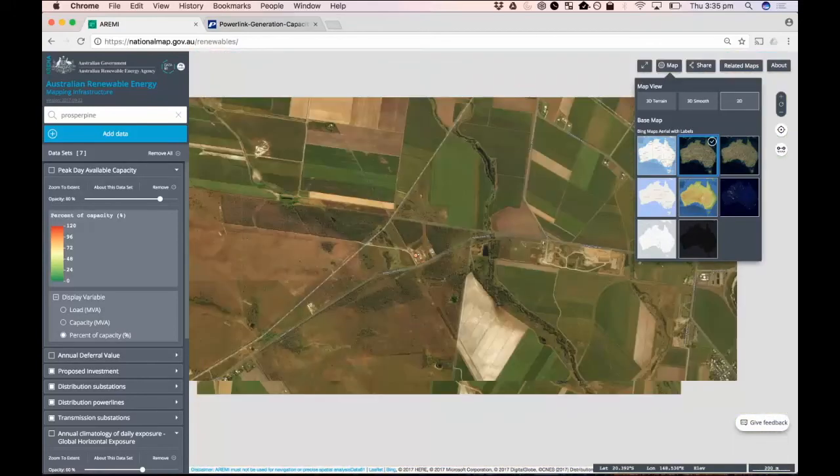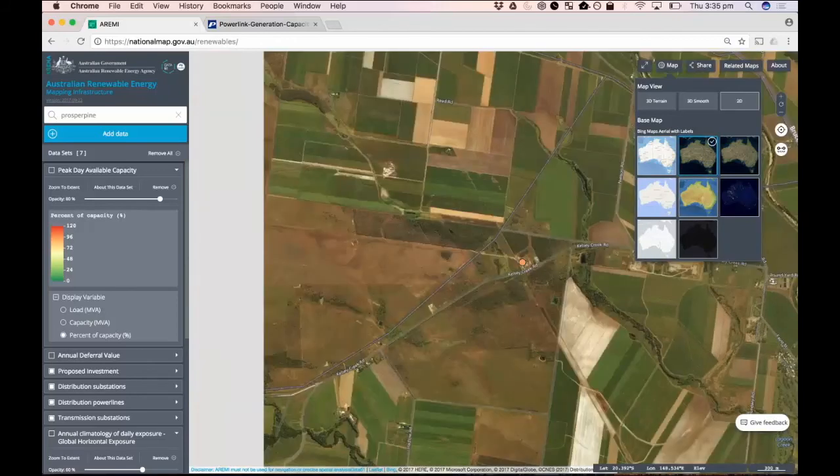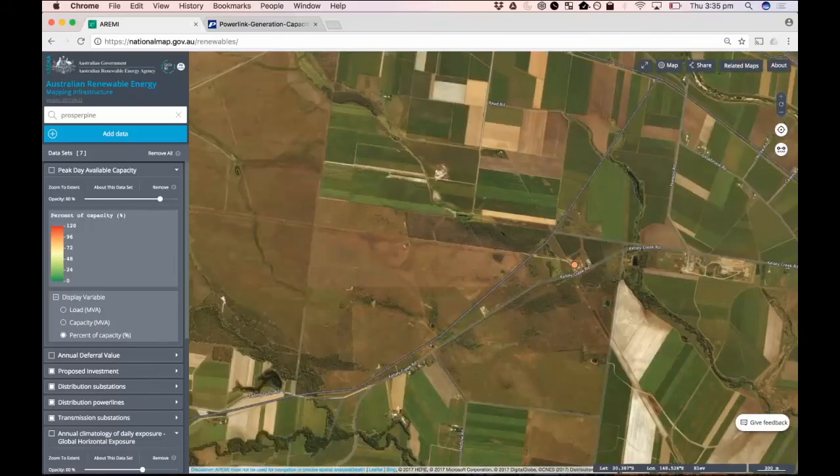You can say, well, between these roads, looks like it's a non-agriculturally used area. That's a couple of kilometres in that direction, and sort of 500 metres or so in that might be in the order of 65 hectares, about a 65 megawatt installation in that particular location, very close to this connection point. Which we know might accommodate something in the order of 75 megawatts.